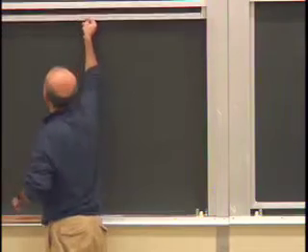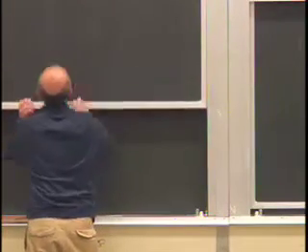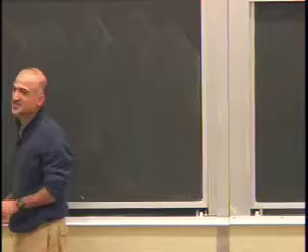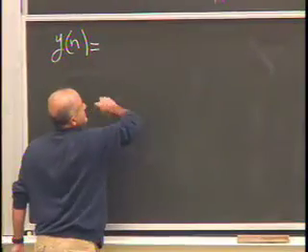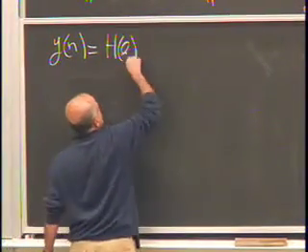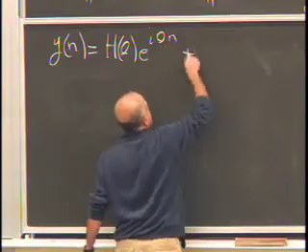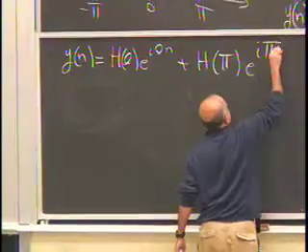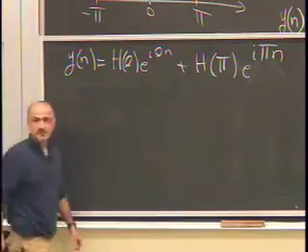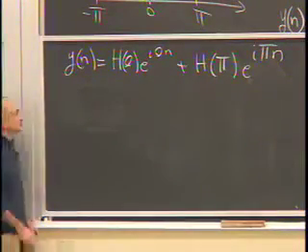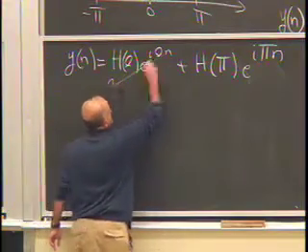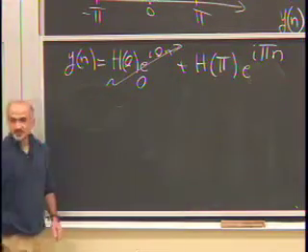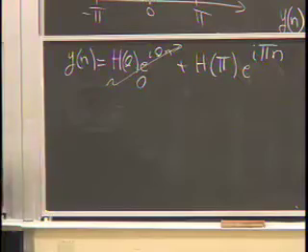Hold on to that thought, Meatball. I've got them exactly where I want them. So y of n, you told me it's got 2 frequencies. So what comes out is h of 0, the first frequency, and the second frequency. Right? We know that. It's an LTI filter. H of 0 is 0. So that goes away. That's how Meatball said we eliminate the 0.